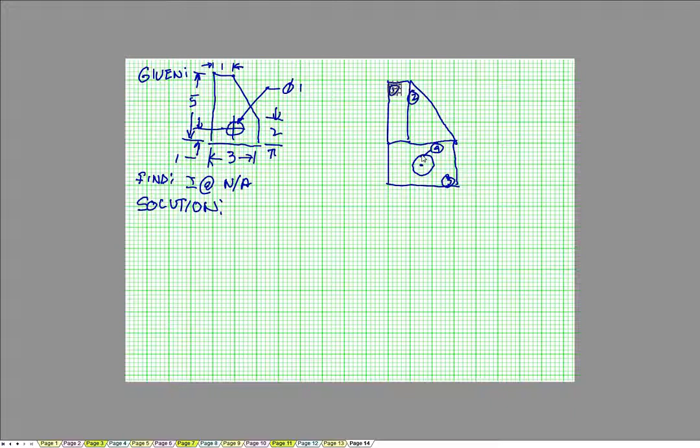Doing a little bit of math here. Let's see the center of both of these pieces. Let's see, that was 2 inches. So that's 1 inch. Let's see, we have the center here and the center here. That's 3 inches tall. The centroid of a triangle is 1/3 the height. So 1/3 the height is 1 inch plus the 2 inches. That gives an overall location of 3 inches there. And then this is 3 inches tall, so that's 1.5 plus 2. So that's at 3.5 inches.